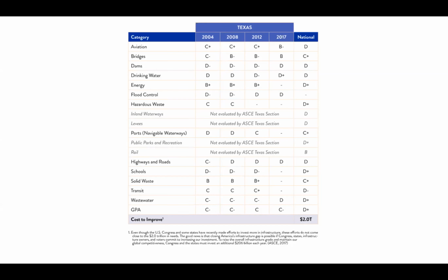Suppose there are 5 girders to a bridge and one of them has poor serviceability criteria and the other 4 are in good condition. In this case, you mentioned that the guidelines are not very detailed and would consider these cases going by worst condition element and not the overall bridge condition. But here you mentioned this approach would need improvement. Why? Do we need to classify the condition of the bridge going by the most critical element?